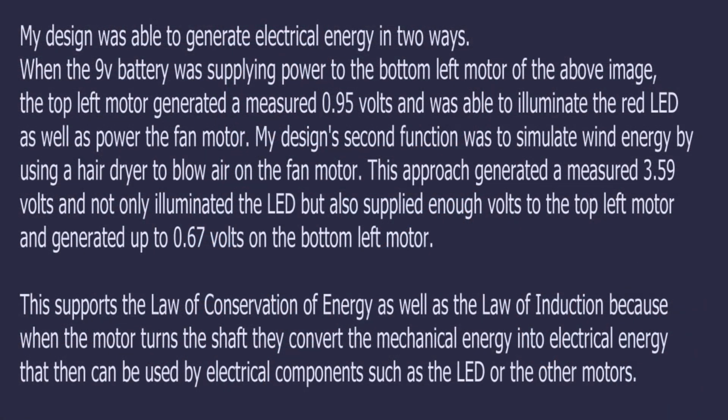My design was able to generate electrical energy in 2 ways. When the 9-volt battery was supplying power to the bottom left motor of the above image, the top left motor generated a measured 0.95 volts and was able to illuminate the red LED as well as power the fan motor.